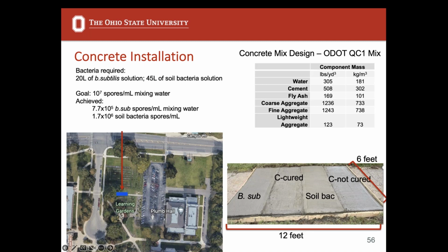Okay, so an additional question: did the cracks only develop in the mortar samples, or the concrete samples as well? The cracks only developed in the mortar samples that we subjected to a flexural load. So they were only where we caused it to crack ourselves. We really just wanted to test and see, could it actually heal the crack, or is this all fake news, you know? And I don't think it is. It looks like they cured pretty well in the right conditions, but there is less evidence in the field.